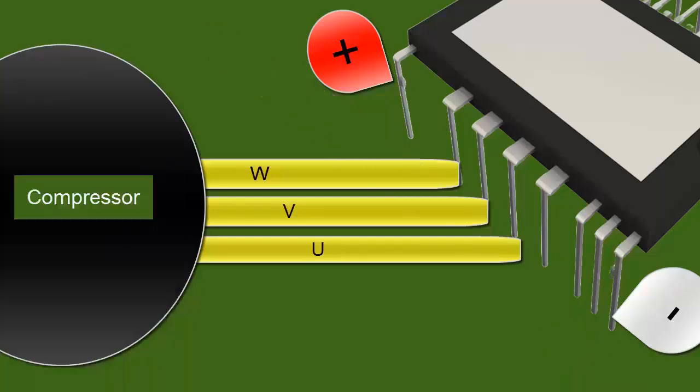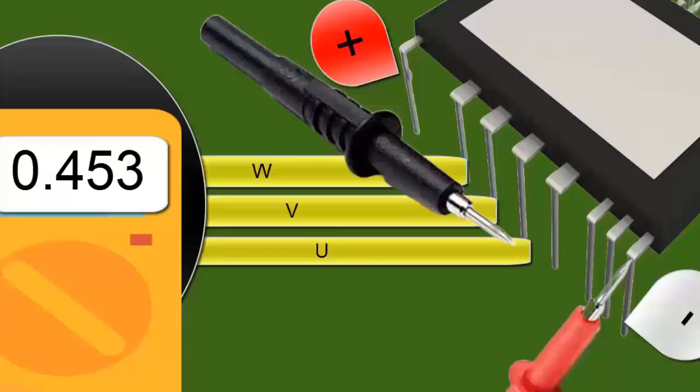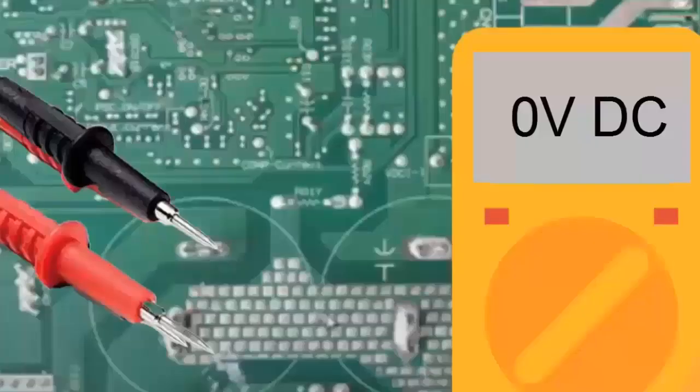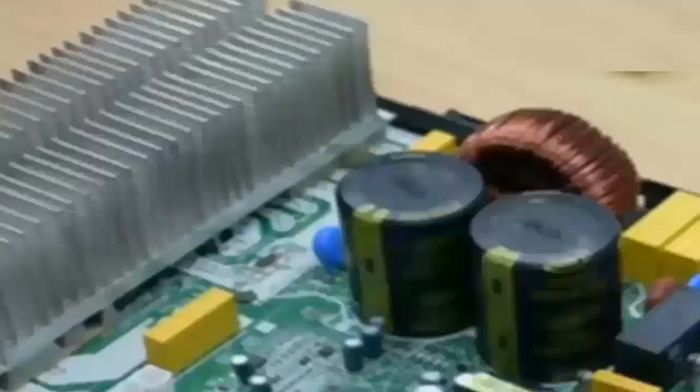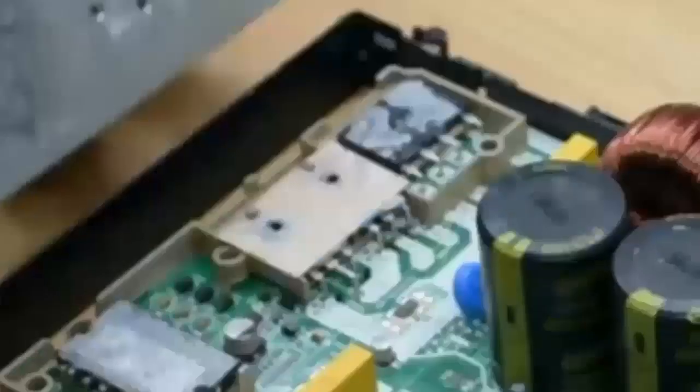If everything seems fine with the IPM electronic circuit, you can perform the following test. Before intervening with the IPM module, ensure the following. Verify the correct positioning of the heat dissipation plate over the IPM. Check the condition of the thermal paste that contacts the dissipation plate.